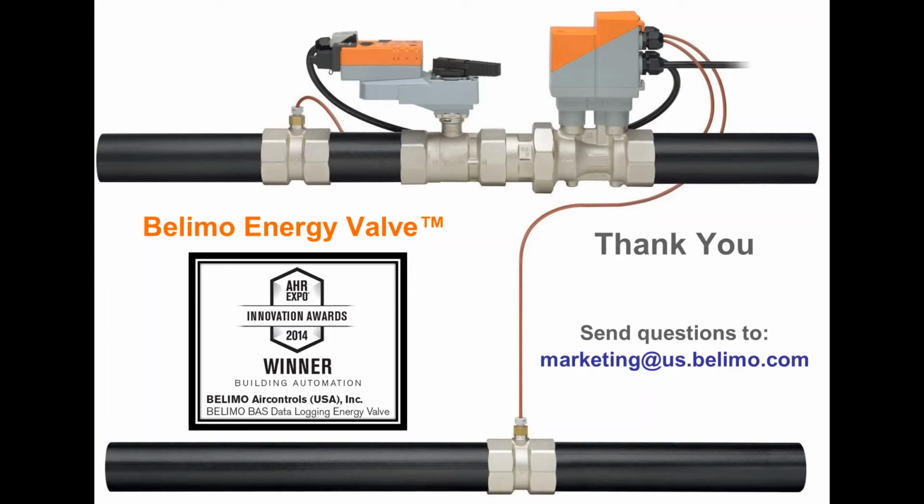Okay. Next question. What is the delta P we have to consider in the energy valve in order to calculate the head pressure pump? Okay, so the energy valve is sold by GPM ratings. In other words, that valve on the screen is like a 2-inch energy valve. I think we can get it's like 75 or 80 gallons a minute through there. But the key is that you can get 75 or 80 gallons a minute through there at 5 psi pressure drop. So you don't need 5 psi to make this valve pressure independent, but you do need 5 psi to hit the maximum flow rate.